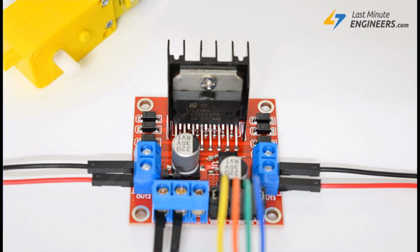Fans. In systems like ventilation and air conditioning, VFDs help control fan speed to optimize airflow, reduce energy consumption, and maintain consistent performance. Conveyors. VFDs enable the control of conveyor belt speeds in manufacturing and material handling systems, improving throughput and operational efficiency. Elevators. VFDs are used to control the speed and smooth acceleration of elevators, providing a comfortable ride and reducing energy usage.